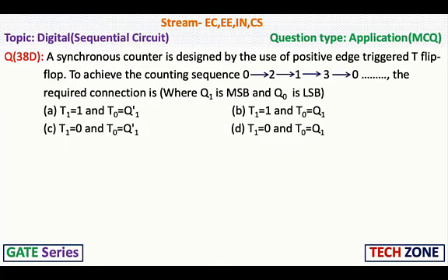Next, a synchronous counter is designed by the use of positive edge triggered T flip-flops to achieve the counting sequence 0 to 2, 2 to 1, 1 to 3, 3 to 0 and so on. The required connection is (where Q1 is MSB and Q0 is LSB):